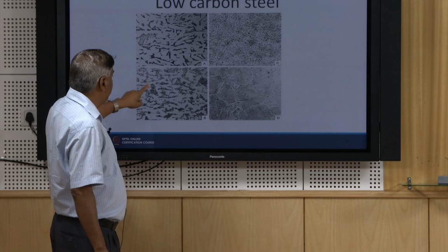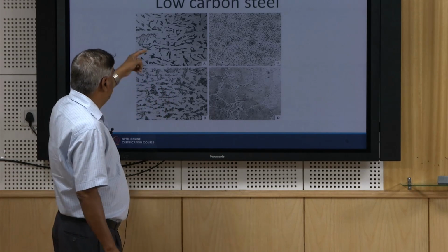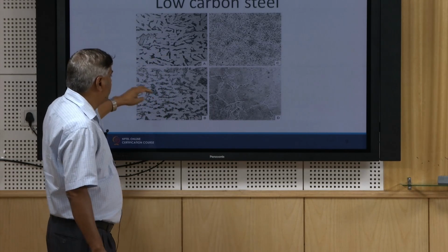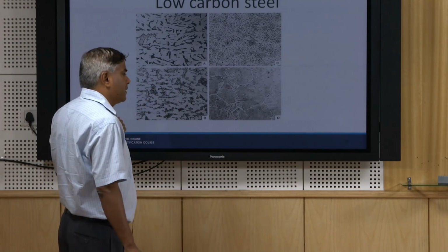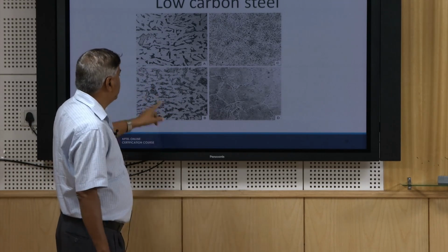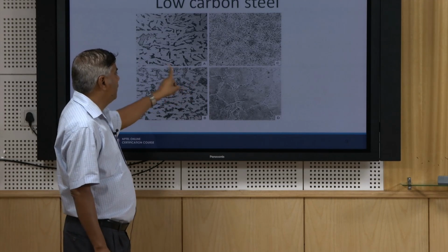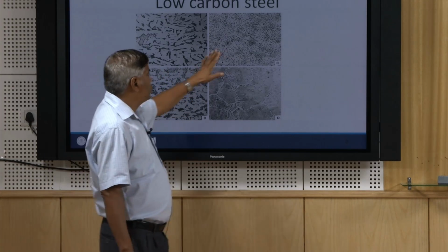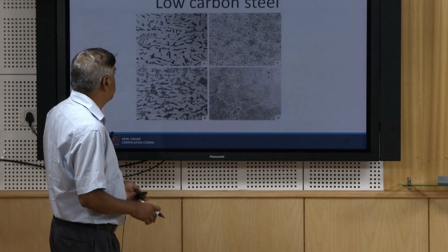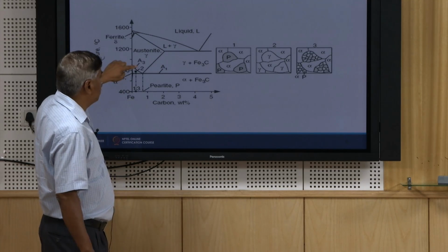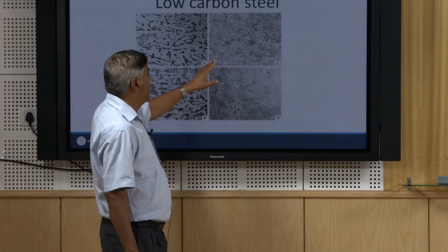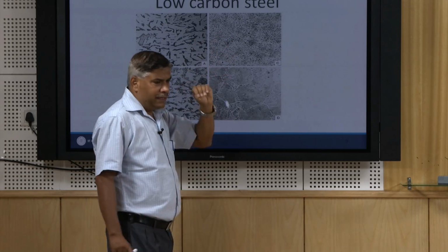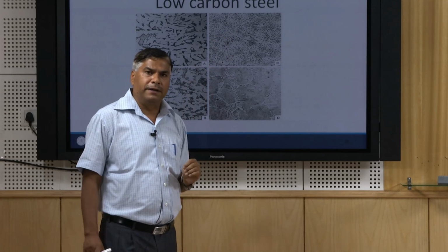All ferrite grains are as they are, and whatever pearlite grains were there converted into austenite, and rapid cooling results in the formation of fine pearlite. Point 3, like, say heating up to this location, as I have explained earlier, is zone C, just above the upper critical temperature.